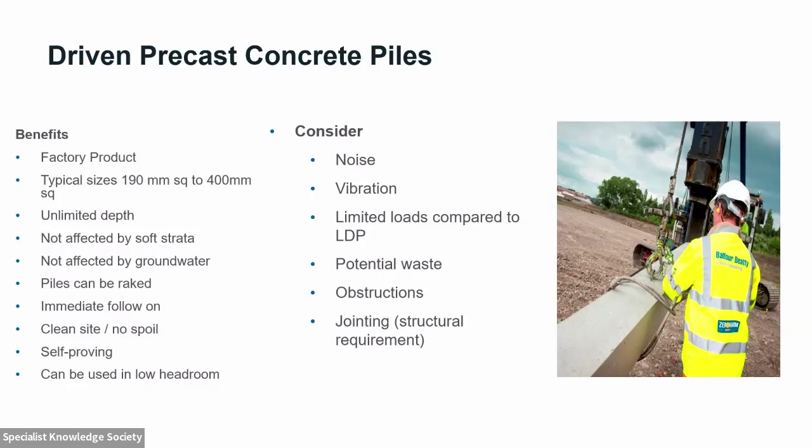And that's really because of how they're manufactured, how they're cast, how they're lifted, and how they're delivered to the site. You get bigger than that and you start to get impractical around the size of pile you can actually lift and then drive into the ground. But that itself then has some limitations on the load that you can put onto those piles. So you can get an efficient pile solution in there, but it does have a limit on the amount of load that you can transmit from your structure down into the ground.